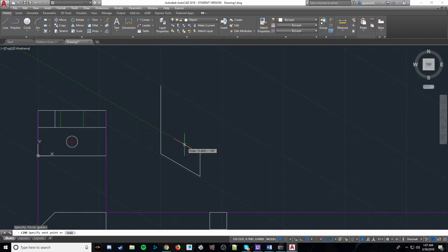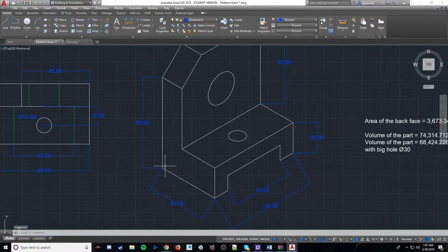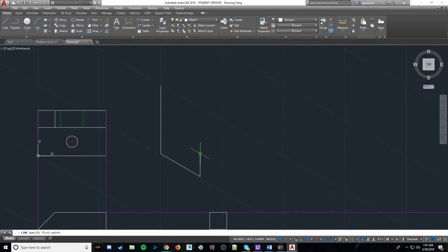So again, this will be at an angle of 30 degrees. So what's the length of that line? It's 40 minus 15, 30, 25. So it's 25. And we're gonna go up. But first we're gonna go over and up. And you notice how I did that?